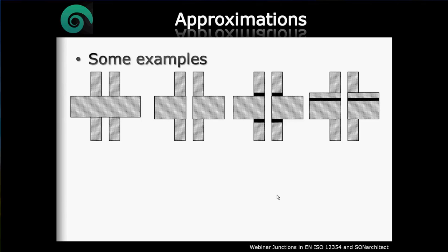The first one is the regular case where we have a double heavy wall on a slab. But if we create a slit in the slab, we can do that simply by adding an elastic interlayer on both sides of the slab. Of course, this will not be the same, but it will behave as an interruption in the slab. So you will find that the results are most similar to some approximations to this flanking path.